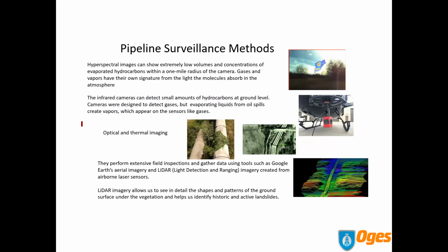Now in the pipeline surveillance methods, quite often, we did this with a couple of oil and gas pipeline companies up in Canada and also in South America now, where we're looking at trying to run drones. And so there's different ways of getting high resolution imagery to identify damage in a pipeline, perhaps the vegetation affecting a pipeline. There's multispectral imagery to identify pipeline right of way, can be used in agricultural space to detect plant health, etc. There's LiDAR to create 3D digital models.